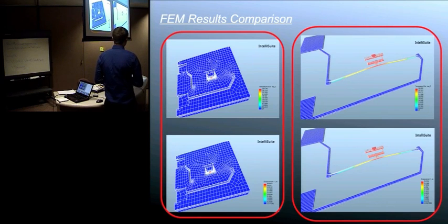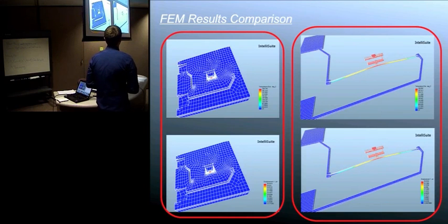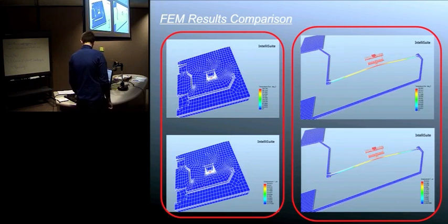It's just a voxel-based simulator that's modeling the additive and subtractive surfaces, adding the layers and taking away certain features. If you use FabSim, which uses more physical-based algorithms, I'll get more into that later, you will have more accuracy when dealing with certain processes like wet etching. In that case, you might see more differences, but in a good way because they're more accurate.